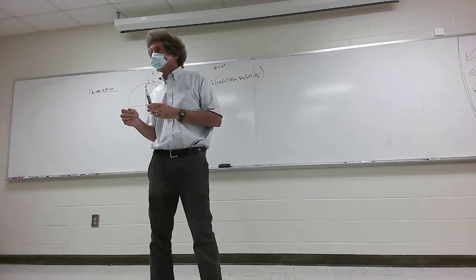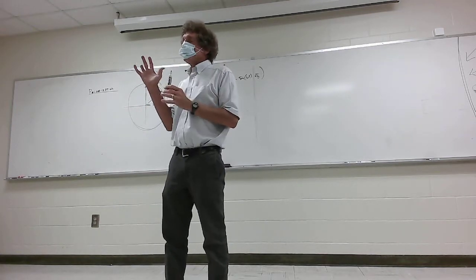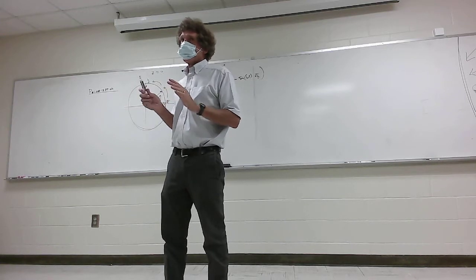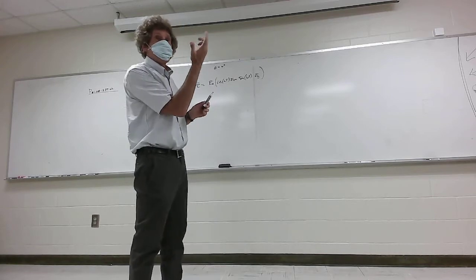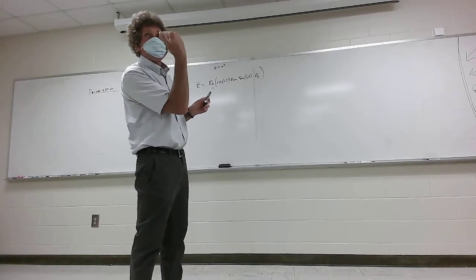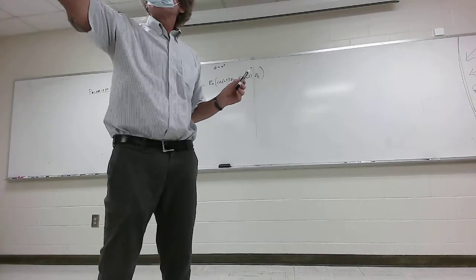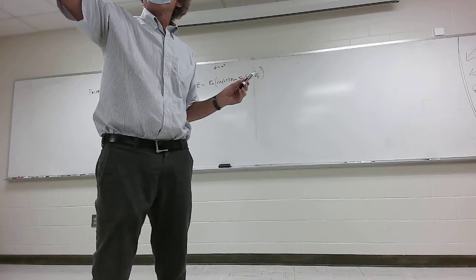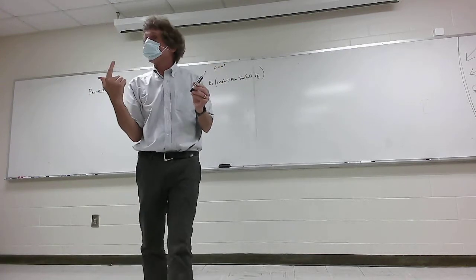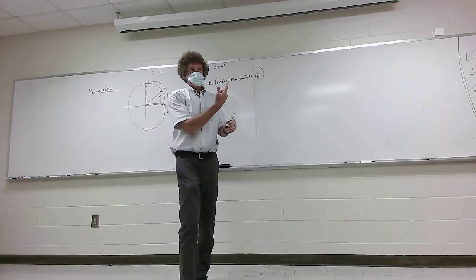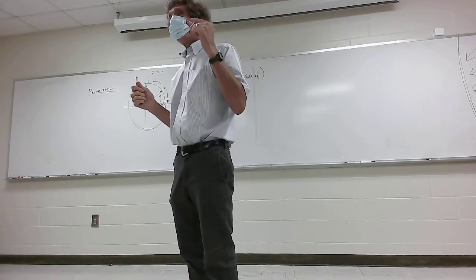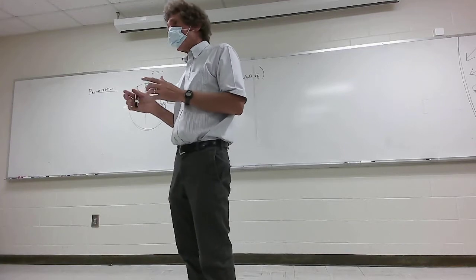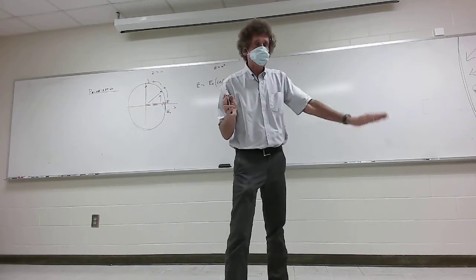And here's why circular polarization is so important, specifically right-hand circular polarization, but we could say elliptical, that gets in the weather radar. When I have a right-hand circularly polarized wave and it's going out, and say it hits a conducting body, say that wall, it reflects back left-hand. Got me on that? So if it comes out righty, it's coming back lefty. Why is that important? I mean, Whitworth's book, he basically glazes over it.